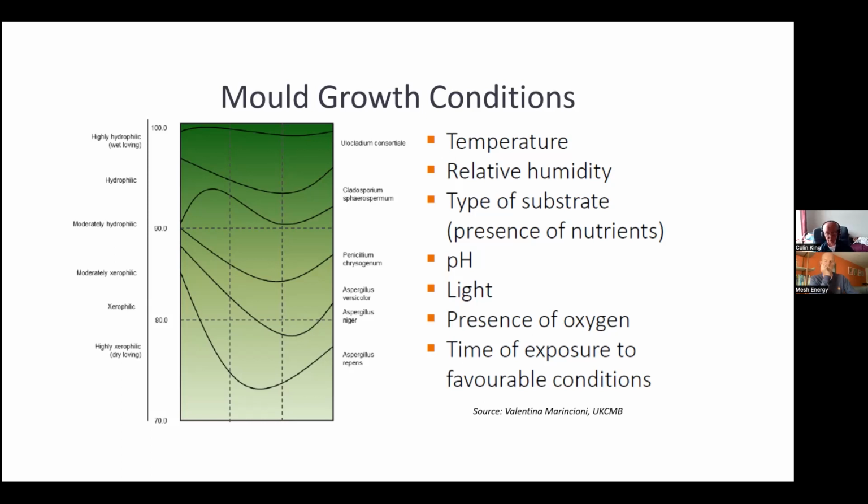But if it's more modern, built of concrete, cement, the idea is you keep the water out. And so therefore the insulation internally, if you put a vapor open on the inside, it would be incoherent, and you'd end up with a higher risk of interstitial condensation because the material is wrong for that structure. So you would use, I don't know, an EPS and XPS. You've obviously got to manage the new issues around fire risk and stuff like that, but mineral stuff like that. It's stuff which is not necessarily hygroscopic.